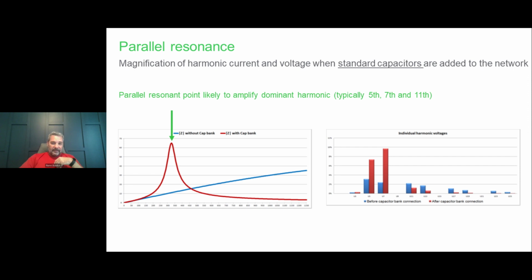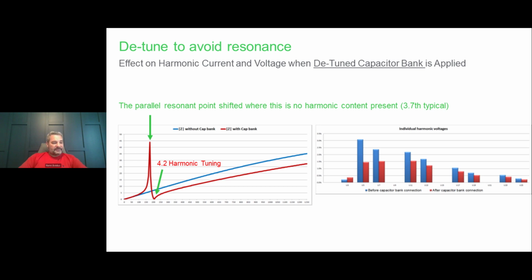So you can see where there is an increase of impedance, the harmonics are being magnified. Here, the big magnification of the fifth and seventh harmonic order. And again, remember that a standard 6-pulse PWM drive generates mostly 5th, 7th, 11th, and 13th harmonic order, so that's why there's a lot of harmonics to magnify here. So obviously, capacitor bank manufacturers had to find a solution to this, to be able to correct power factor in a harmonic-rich network.